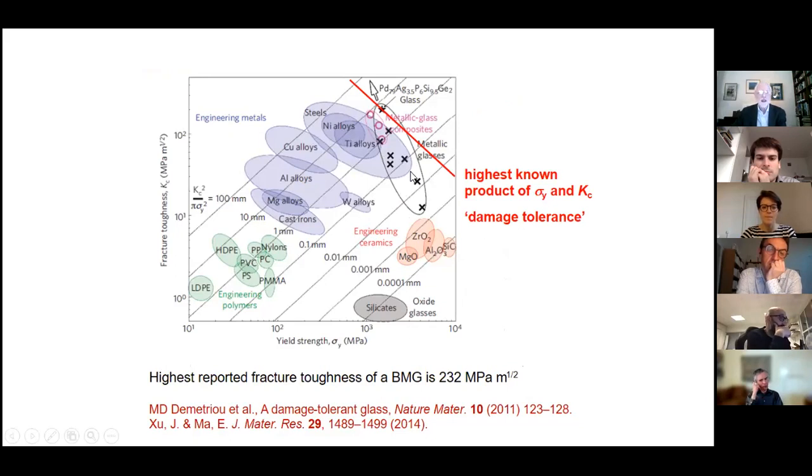You could anneal the steel, you would reduce its strength, which might seem to be a bad thing to do, but the steel would automatically get much, much tougher. It would be much more resistant to cracking. So in these conventional materials, you always have this trade-off. Do you want a high flow stress of the material, or do you want a great resistance to cracking? And by and large, you cannot have both. And steels are the classic example of that trade-off.